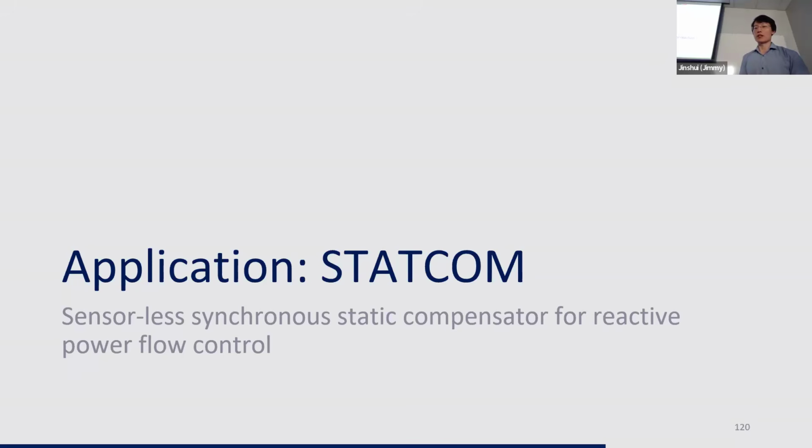And they usually prefer a modular structure to deal with massive voltage and power. In this section, I'm going to introduce a new StatCom solution with our 4040 topology to take care of the module balancing problem, which can make the system more robust and reliable.